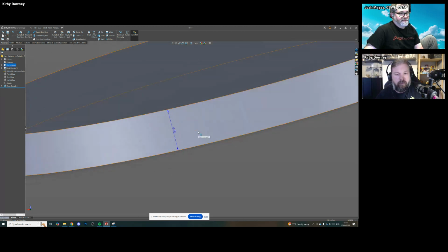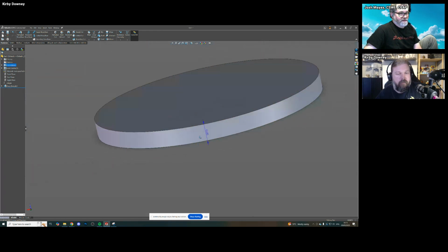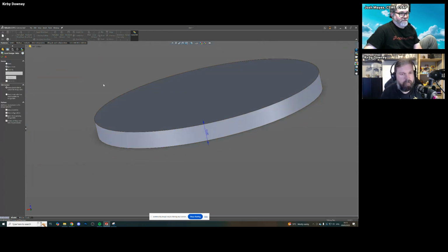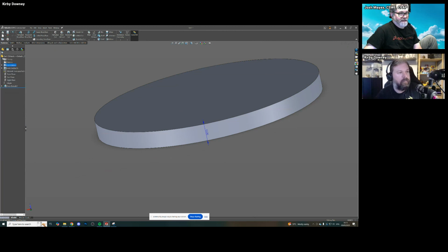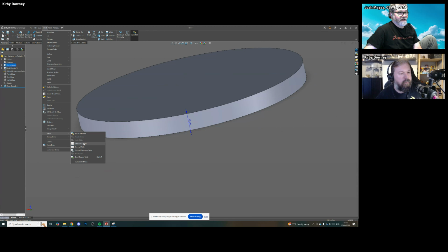So if you open that design table up and that is visible on your screen, you can hold control and pan around behind that window without exiting it, though it's a little tricky. If you set it up so your design table and your model are both showing on the screen at the same time, you can double click on that dimension and it will add to the table.